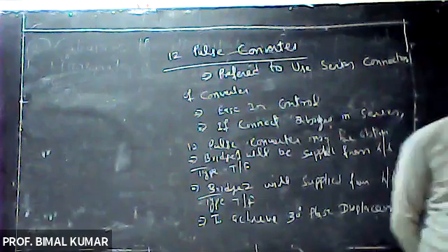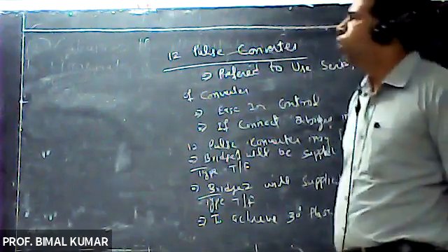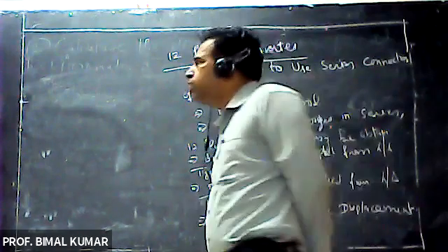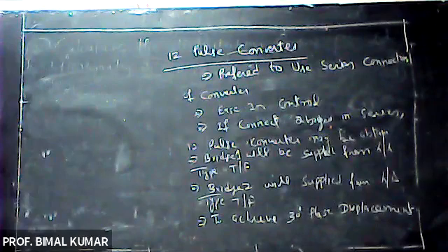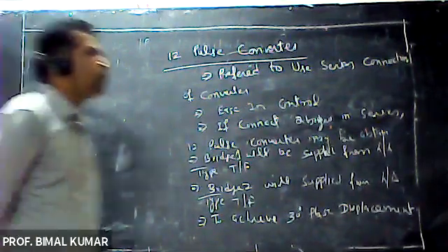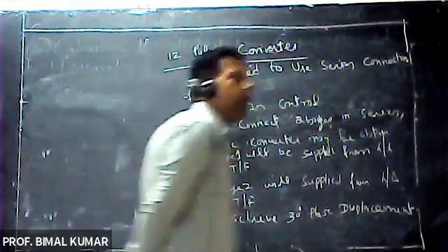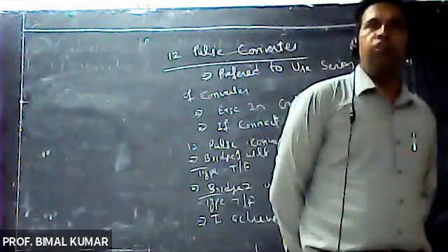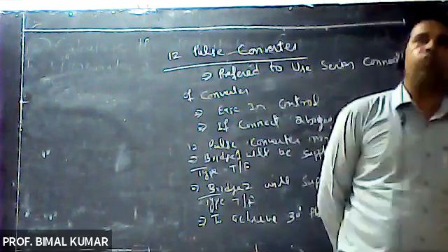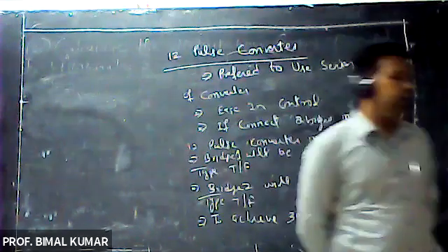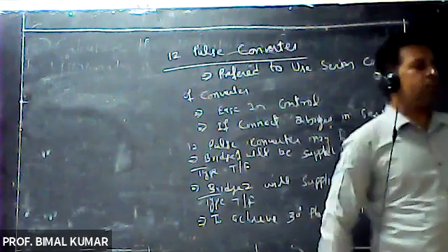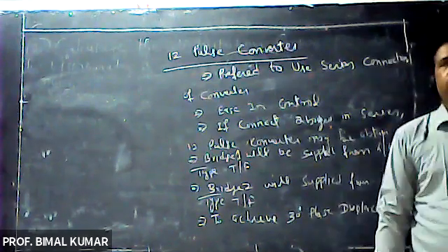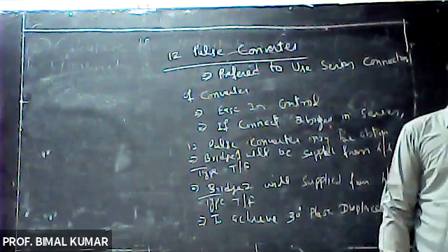And this is due to imbalance of the supply voltage, because if we are using 18 or 24 or more number of pulses, then your supply voltage will become imbalanced, and we are not able to eliminate that non-characteristic harmonics, right?